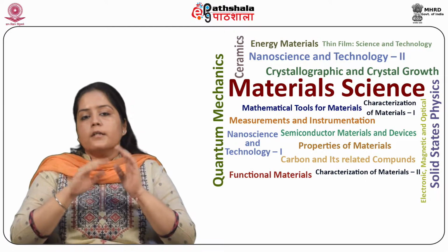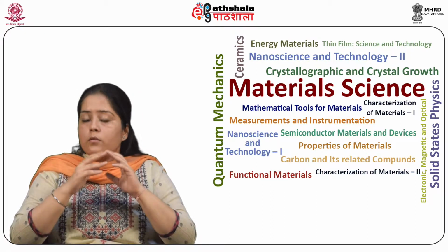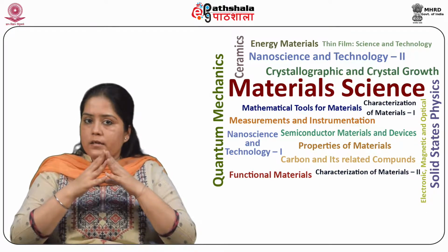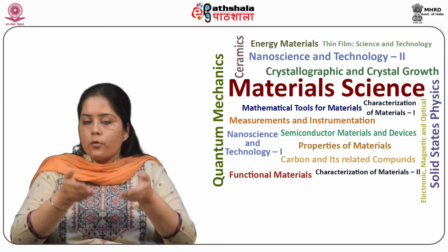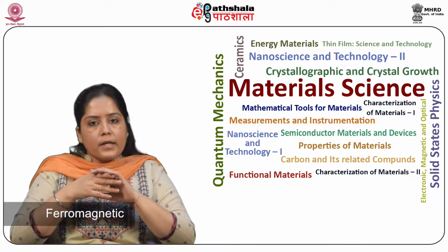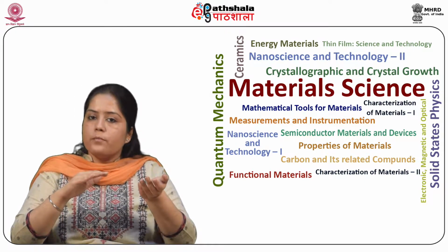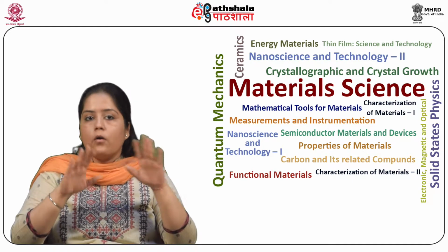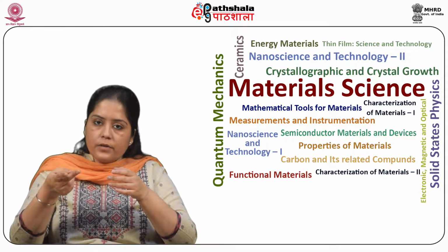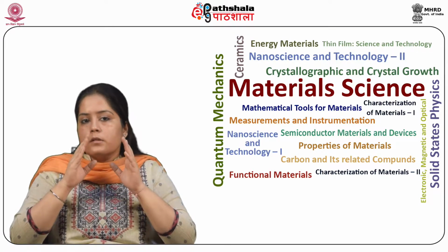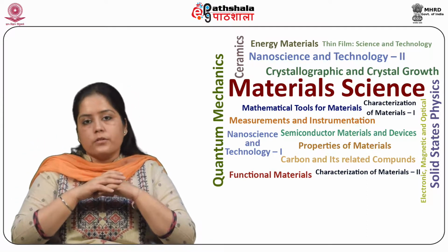On the other hand, the magnetic behavior of metals is rather complex and it also belongs to the category of paramagnetism. Let us take an example: iron, cobalt and nickel are ferromagnetic at room temperature. Chromium and manganese are antiferromagnetic while the rest are para or diamagnetic. The transition metals are ferro, antiferro or paramagnetic, with those ferromagnetic becoming paramagnetic above their Curie temperature.